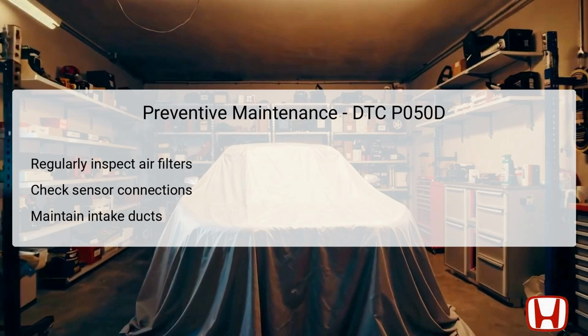It's advisable to replace the air cleaner element as part of routine vehicle servicing based on manufacturer recommendations. Additionally, frequently checking sensor connections, specifically ensuring they are free of corrosion or damage, aids in maintaining accurate readings, preventing misleading information to the PCM.